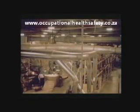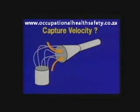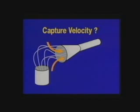Let's look at how good industrial ventilation systems are designed and installed. At the beginning of the design process, important questions are answered. At the emission source, one question is, how fast must the air travel to capture or contain the emission source? The answer to this question tells us the hood capture velocity.